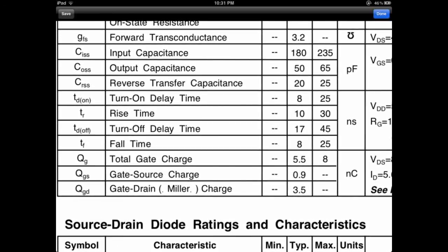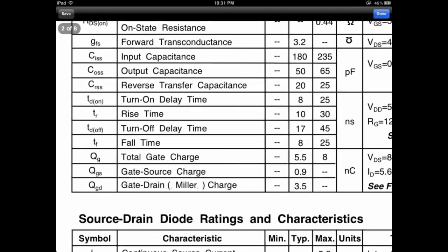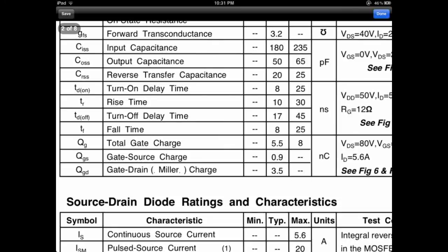That's telling you how you use that to figure how long it takes to charge the gate, to actually draw those electrons up into the channel. And like I said, most of you dealing with microcontrollers where you're just turning stuff on and off, you're never going to probably get into this. But if you get into stuff where things need to be done quickly and very speedily, then this stuff starts to play. So I just want you guys to see it and have me explain a little bit of what it is. These gate charges may have some significance because you have to bleed that gate charge off, or you have to charge it.